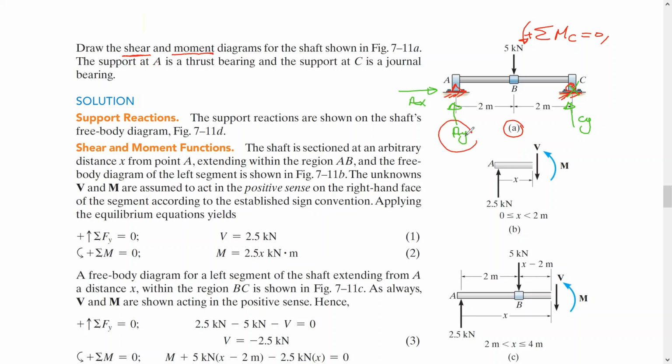So in this case, we have AY here. It will rotate this clockwise, so it's going to be -4, and 4 is this distance, AY, plus this force will take the beam to the counterclockwise, plus 5, the magnitude of this force, times 2, and this one will equal 0.